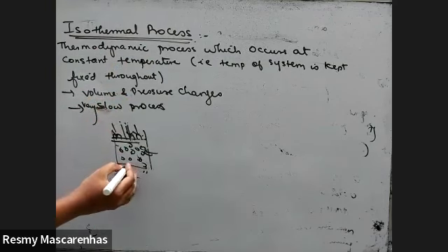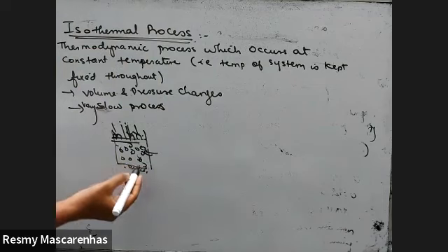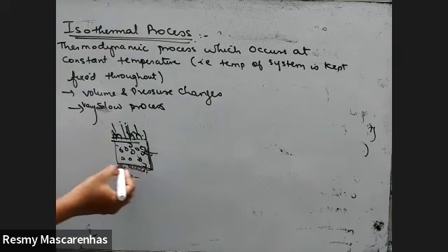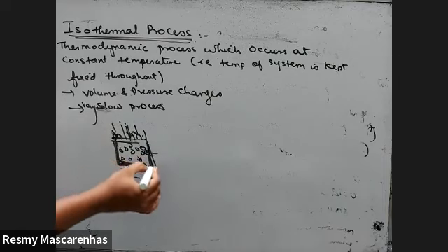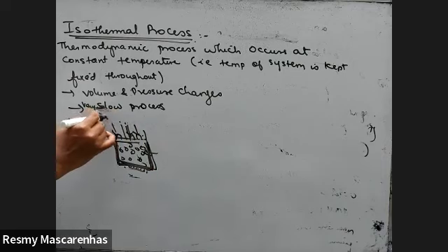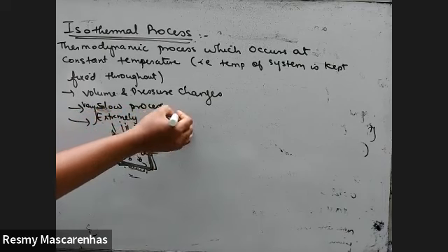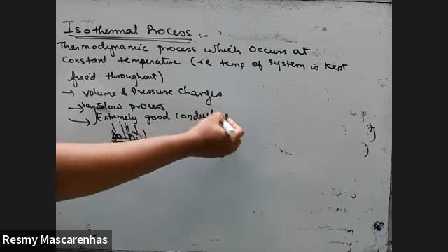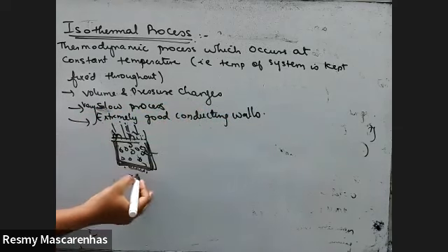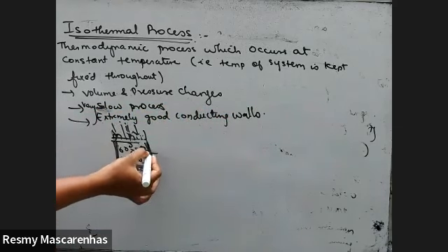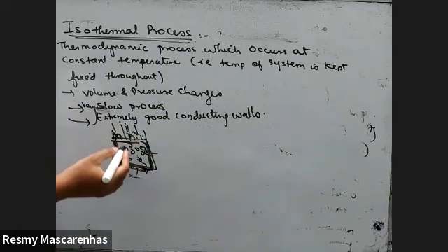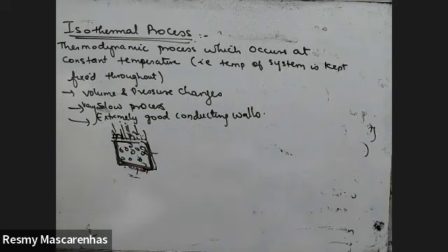Why? You have to provide very little heat at a time, so that these walls are conducting. Write this also, conducting walls it should have. So this very small heat will directly pass through the wall, and the small energy which you are supplying to the system goes into pushing this piston up, because there is some load put here.